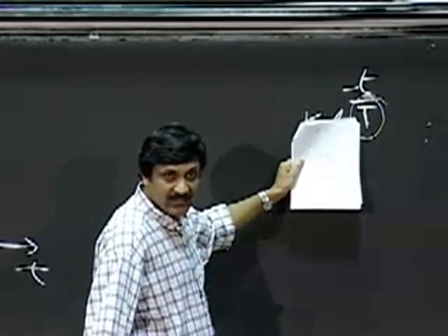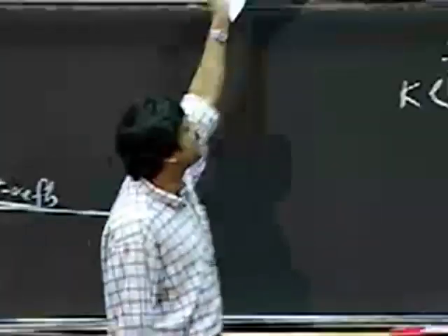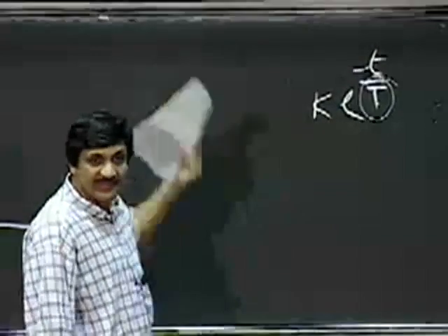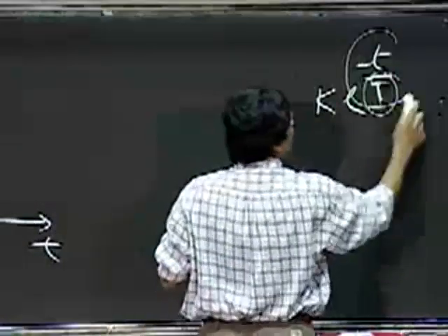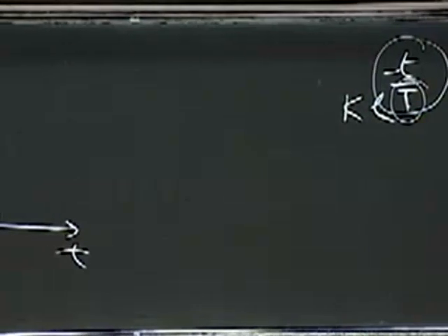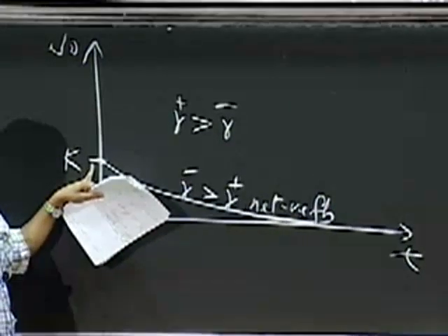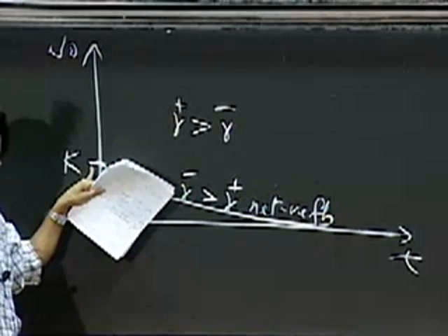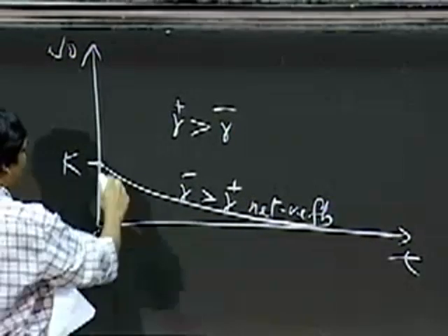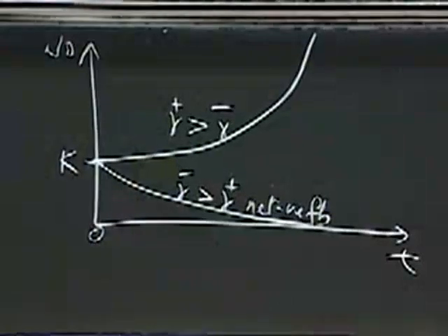Now, we cannot see this happen in an RC circuit because capital T is equal to RC. But here we have a more complicated circuit, and capital T can go negative. If capital T goes negative, then the whole thing in the exponent goes positive. If that goes positive, what should the output look like? It should go up, it should take off into never-never land.